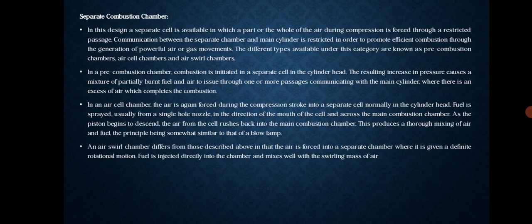An air swirl chamber differs from those described above in that the air is forced into a separate chamber where it gets a definite rotational motion. Fuel is injected directly into the chamber and mixed well with the swirling mass of air.